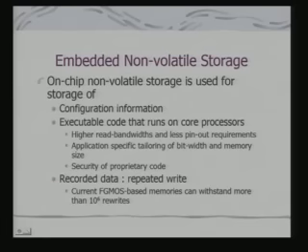You can have application specific tailoring of bit width and memory size, because you do not need to make it compatible with available flash chips and their configurations. The other interesting and important thing is security of proprietary code. Since it is sitting inside the chip, it becomes difficult to access and know what the code is all about, and then do some kind of forgery, in the sense of taking the code and using it for other purposes.